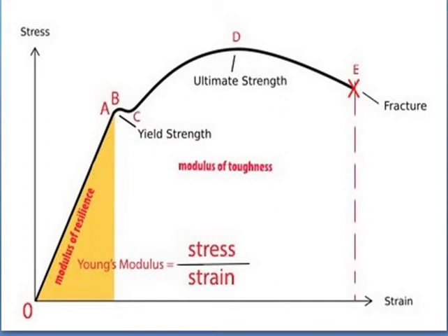The stress is determined by dividing the load values by the original cross-sectional area of the specimen. The elongation is measured by determining the amount that two reference points on the specimen are moved apart. The original distance between the two reference points is known as gauge length.